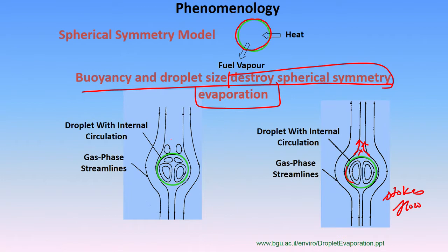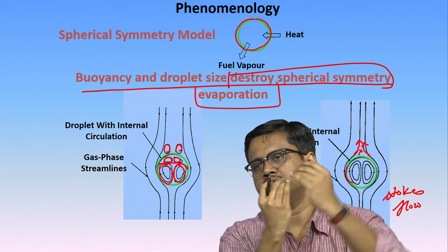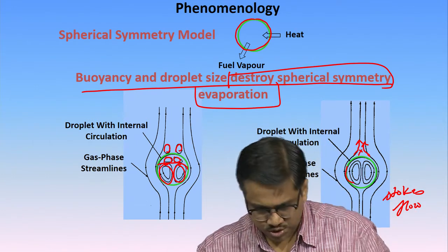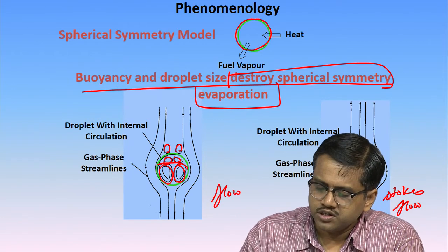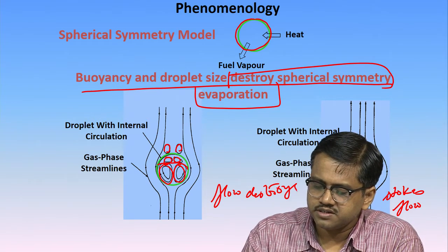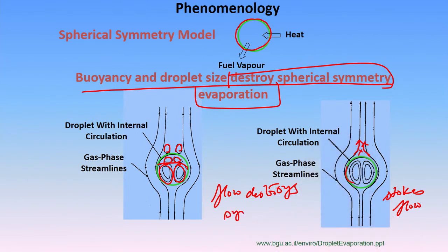If the flow shows any separation in the aft of the droplet, you basically get an asymmetry, where you have these four lobes. It is once again two vortices. One is a toroidal here and the other is a toroidal on the top. So, it is segregated into two. So, it destroys the symmetry whenever you have a flow. So, flow destroys the symmetry, inducing what we call recirculation.